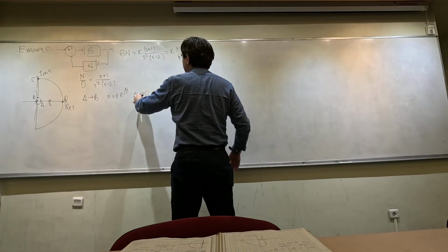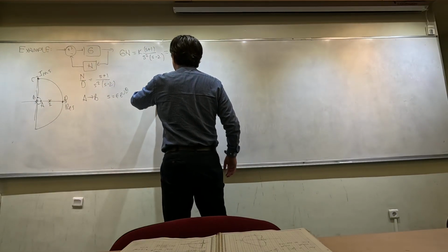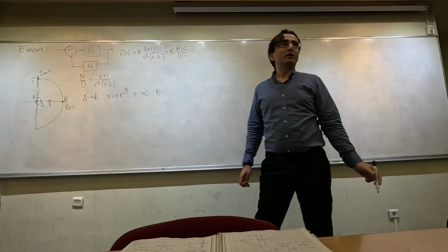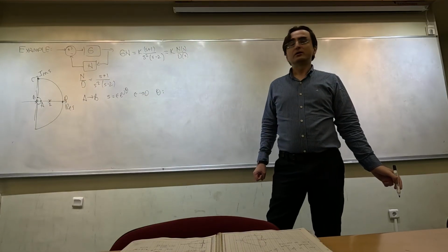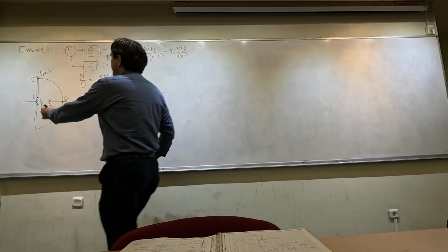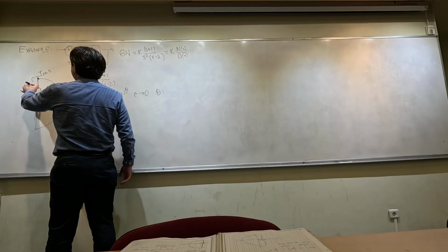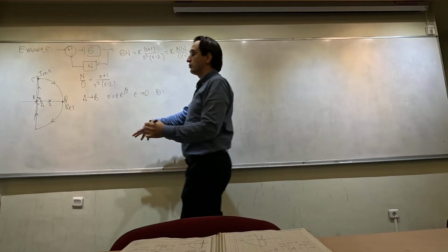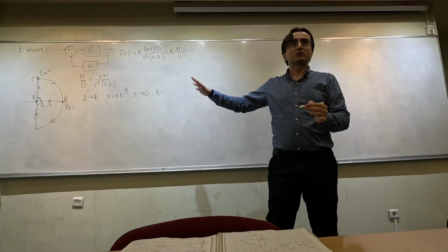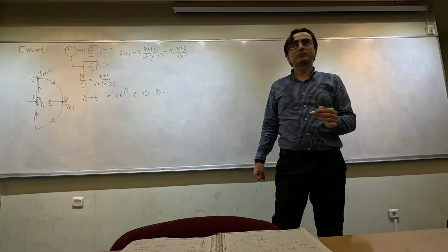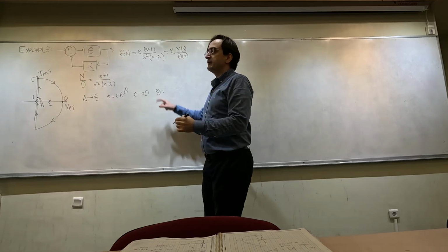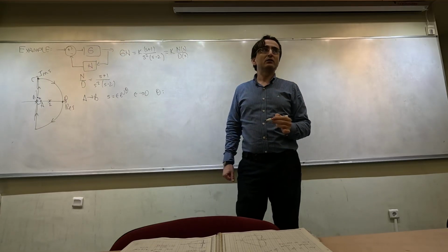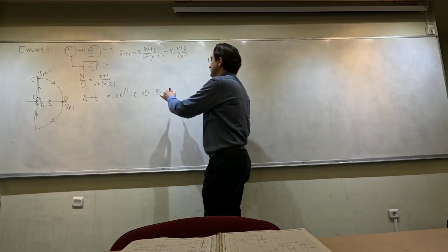Epsilon goes to 0, and theta changes from where to where? From A to B. I have to put directions here always. So this is a clockwise contour. That is why I'm always checking. After drawing the Nyquist plot, I need to count the clockwise encirclements of -1/k. So here theta is going to change from where to where? Sorry?